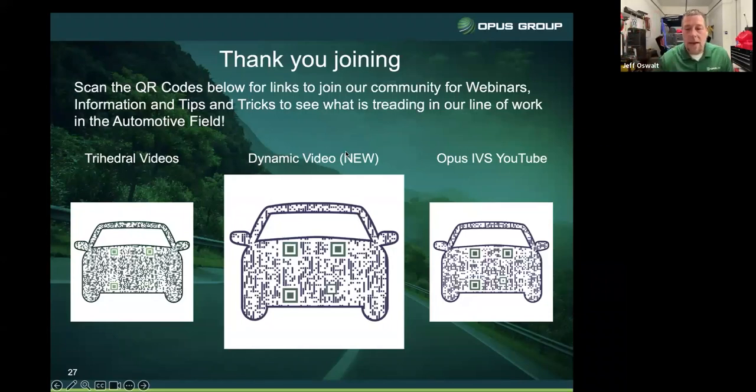So I had a Honda. The very last car I did was a CRV, busted windshield, had A-pillar problems. They had to take the windshield out and put the windshield back in, so it qualified for the camera calibration. And the car was hit in the front, so the radar was damaged behind the emblem. It got replaced. So that car got a 4-wheel alignment. It got a full tank of gas. And I gave all that documentation to the insurance company. I never had an insurance company not pay me for something. If it's in black and white, I always got paid, and so did the shop.